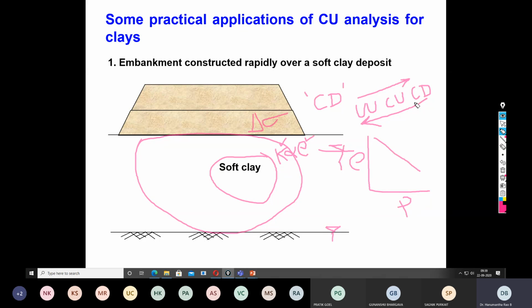Okay. Because of this small degree change, if there was no surcharge, this condition becomes more prevalent. This is one of the reasons that whenever you construct any embankment using surcharge load, but after removal of the surcharge you don't construct a permanent structure on top of this consolidated soil, and you give a long gap between the removal of the surcharge and the construction of the superstructure, there may be a possibility of failure again.